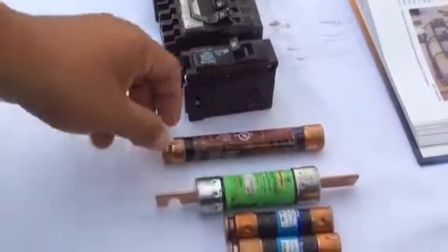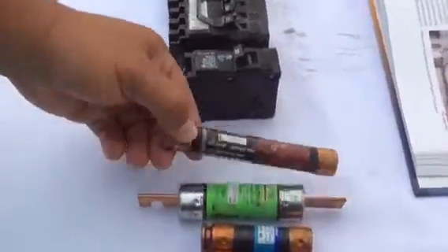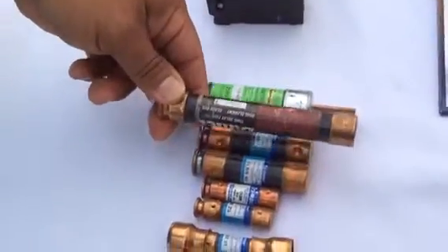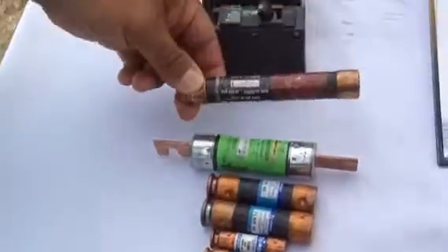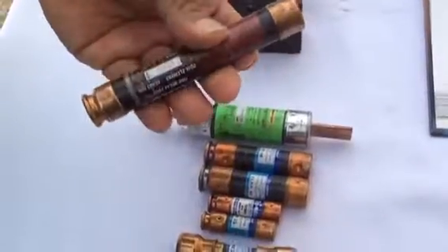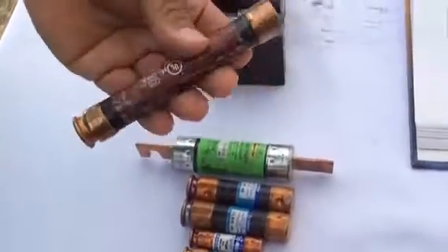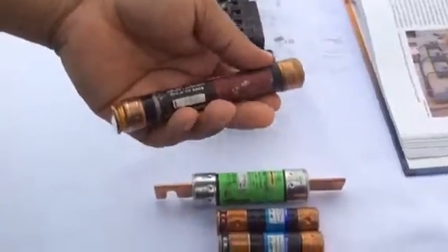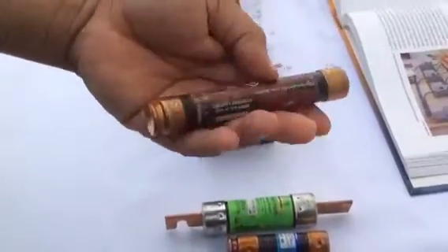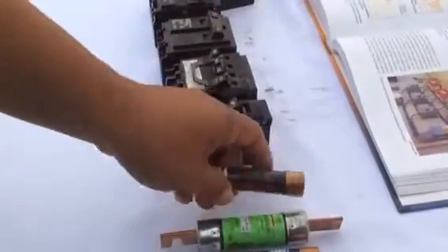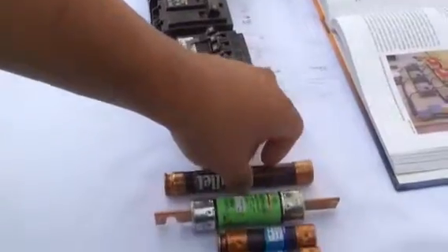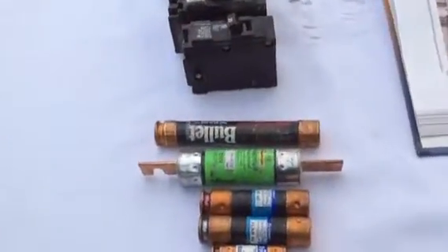This is a 100 amp. And something curious, this one is way bigger than those two, but this is only a 15 amp. The reason they get away with that is because this came off of a three-phase system, where you can go with less amperage, and so we have three fuses with 15 amps on them.